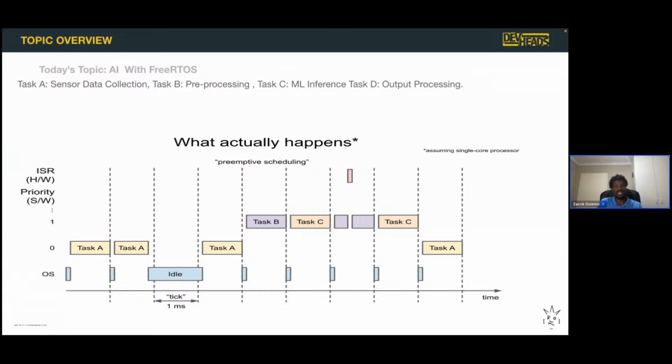But I could start moving and then suddenly do a gesture action and it needs to pre-process, and after that it would recognize the gesture and move it. And as I said, as we are shaking the mouse, it's still expanded and it's still expanding. So we could have more work coming in while we are doing the work that currently needs to be done. So that's why we need a real-time operating system that is basically swapping around all the tasks and keeping them all running in such a state that we are always achieving what we need to achieve.